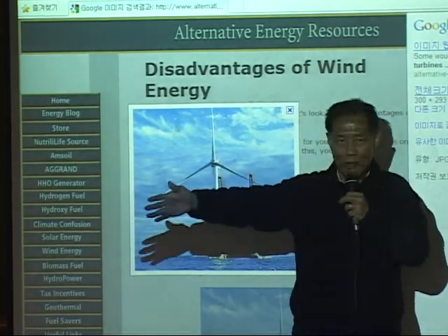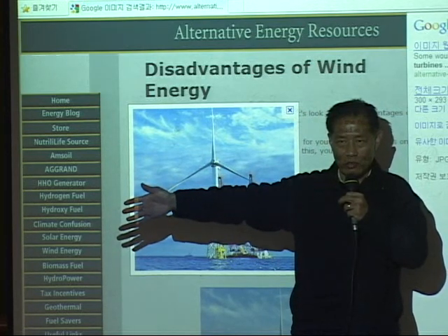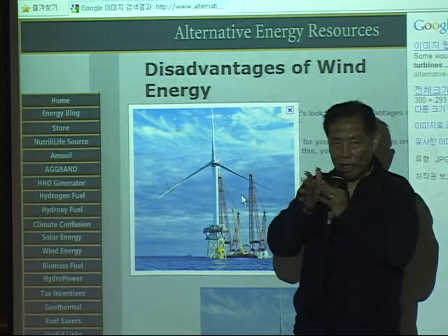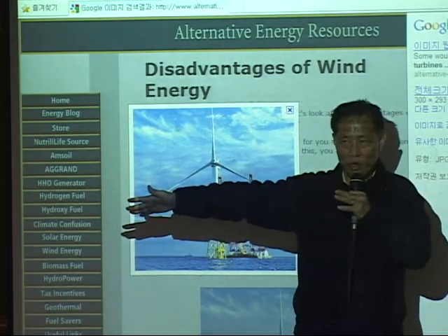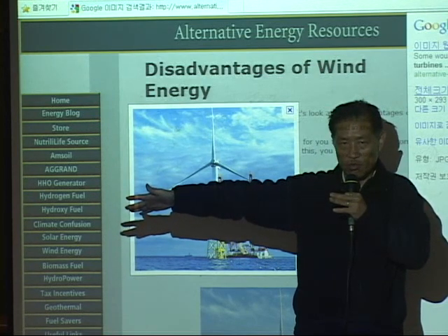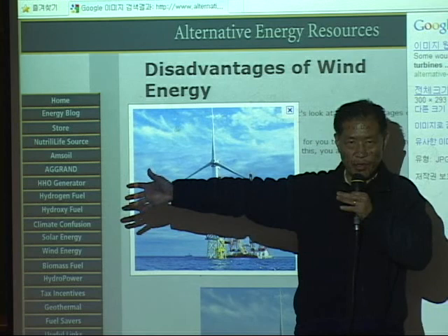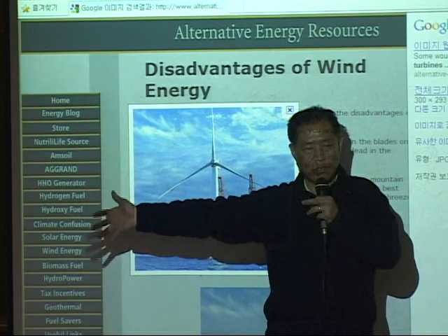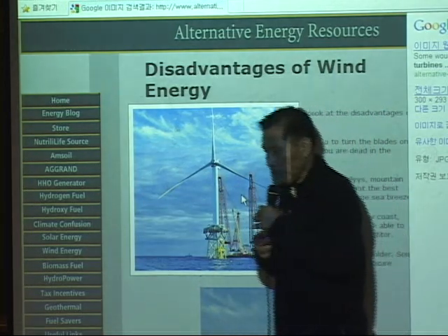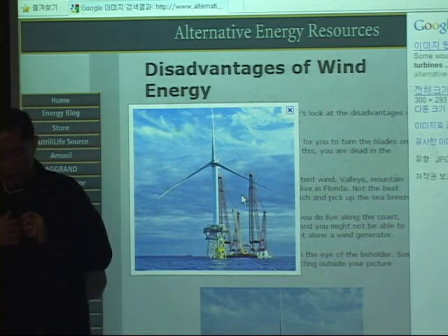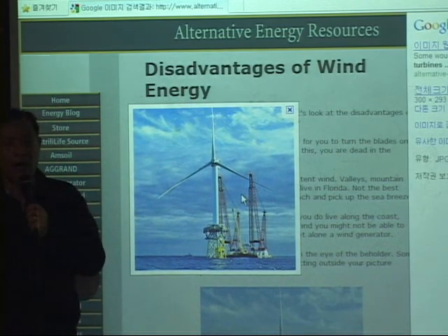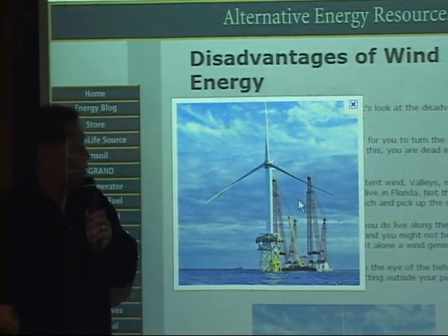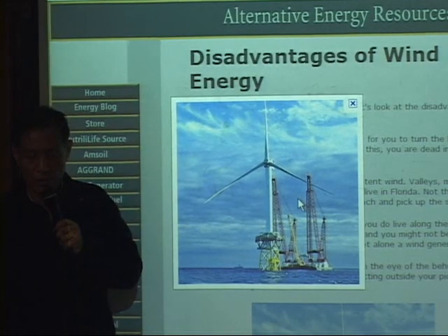But not only bending, it is also subject to a torque like that. When wind is applied to the surface, it will be subject to a torsion. So this blade will be subject to a lot of torsions, and you need to understand how to design and how to calculate the stress and angle of rotation by understanding this torsion theory.